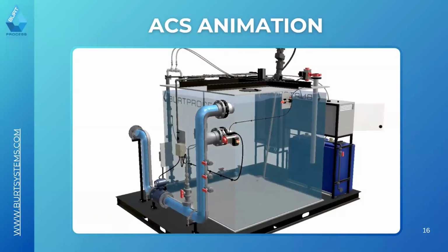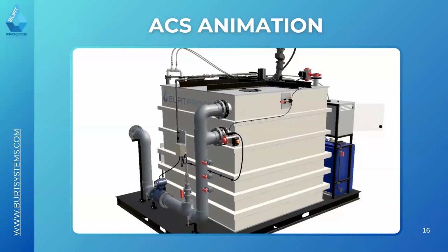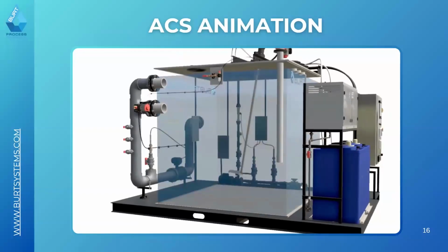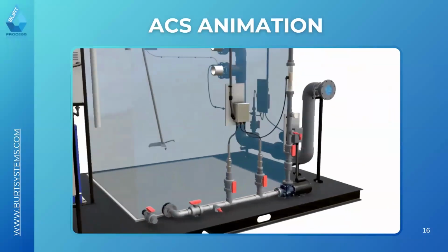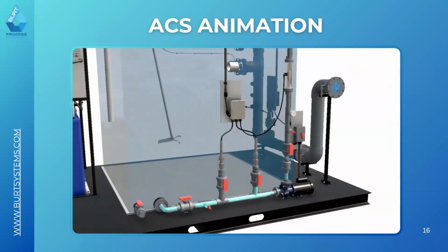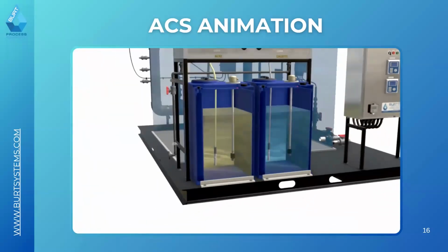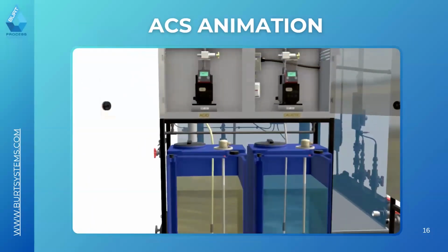Most people associate this with raising the pH of the waste stream to like 13.5. Really nothing can survive biologically in very high caustic environments. We've done a lot of work in some different facilities, even the U.S. government, for example. What they do is both raise the pH very high and cook the waste at that point. You can destroy any biological residue at that level.